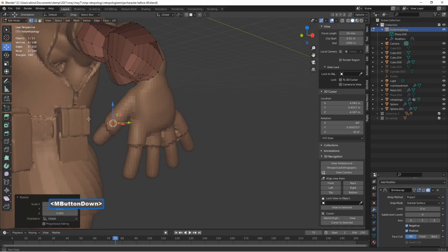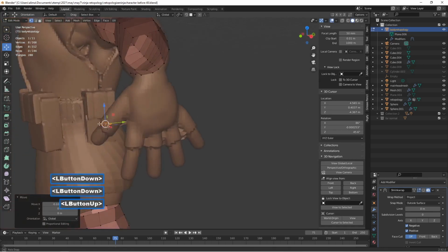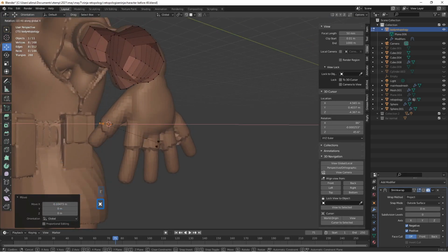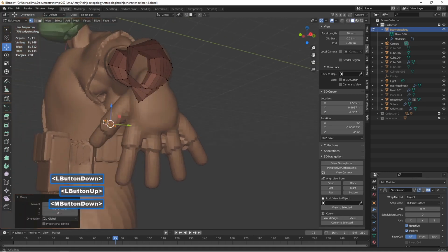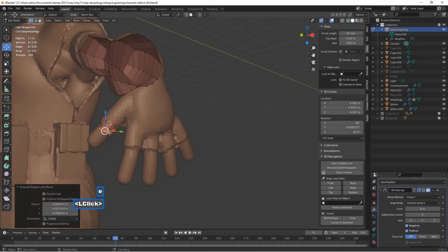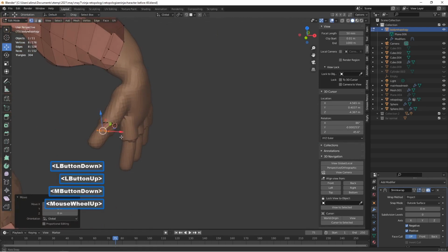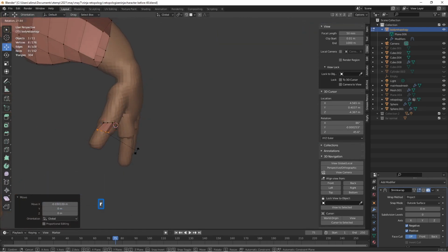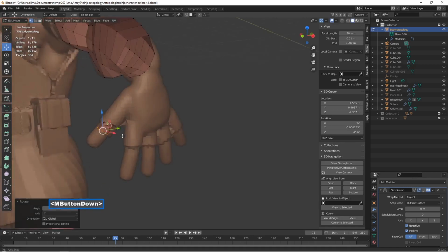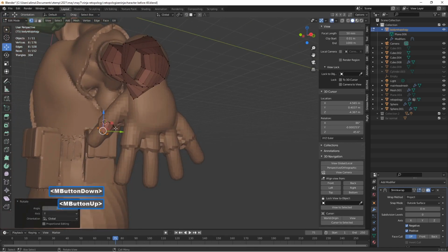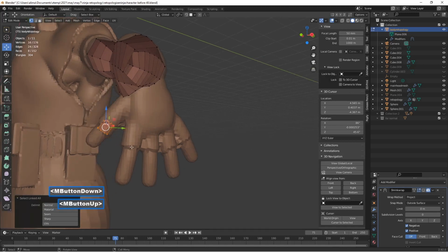Putting this inside, shrinking this down, pushing this inside. We'll press R to rotate on the X-axis this time. Position that inside. We'll press E, extrude that down some, make sure that that's inside. We'll press R on the Y-axis. Well, because we have this selected, we can hold control, then press L. That was control L. Once you're selected on vertex or vertices, you press control L, you'll select the rest of the geometry.